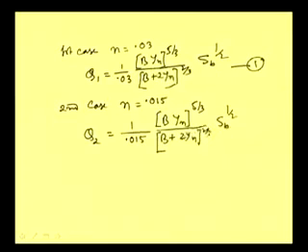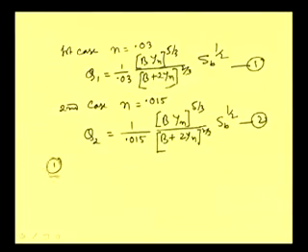Now, our interest is to know what will be the increase in the discharge. So, just by dividing 1 by 2, we can have Q1 by Q2 equal to 1 by 0.03, other things remaining the same and getting cancelled, divided by 1 by 0.015.